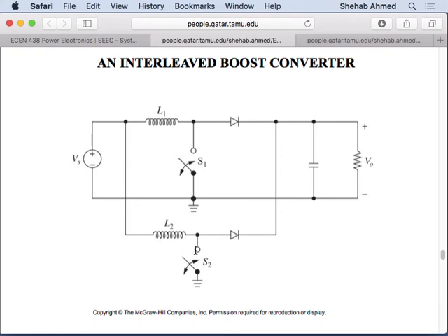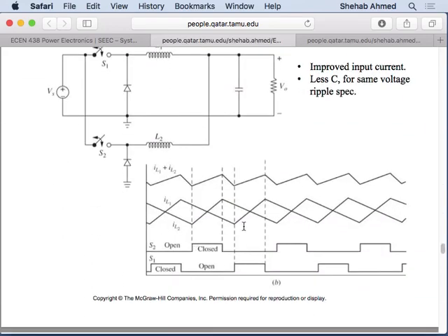The idea is putting power supplies in parallel, but phase shifting the waveform so that it makes something useful for you. You don't need to phase shift the waveforms, right? Because if you add the average value of current from supply 1 plus the average value of current from supply 2, it will be the average value of current that you require. At the end of the day, you require an average value of current because you have a DC-DC converter. You're looking at the average value of the current that's output. If you don't phase shift them, you get the same average value but with the same large ripple. So why not phase shift them and get less ripple for no cost? That's what this is saying, right?